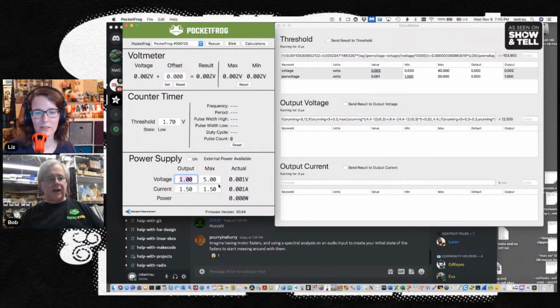And we have the power supply. So you can turn the power supply on. We have safety limits. You can just use a scroll wheel and just dial it up. It goes against your safety limit. It's a 20-volt power supply. It can run off just plain USB. It'll still give you 0 to 20 volts. You can use external power, and it'll give you up to 40 watts of power.